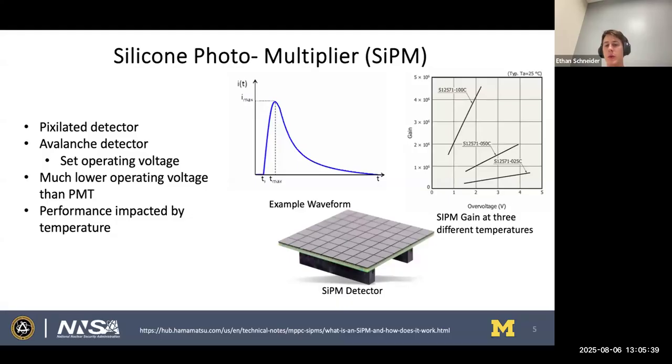With a PMT, the smallest one we have in our lab personally is around 1.5 inches in radius, as opposed to this SiPM, which is on the order of 20 or so millimeters, I believe. So you're able to have a much more dense system here in comparison to those photomultiplier tubes if you want to have many detectors close to each other, as seen by that dual particle imager. And it's also a lot more compact. So you can have all these channels onto a single board. So there's a lot of advantages there.